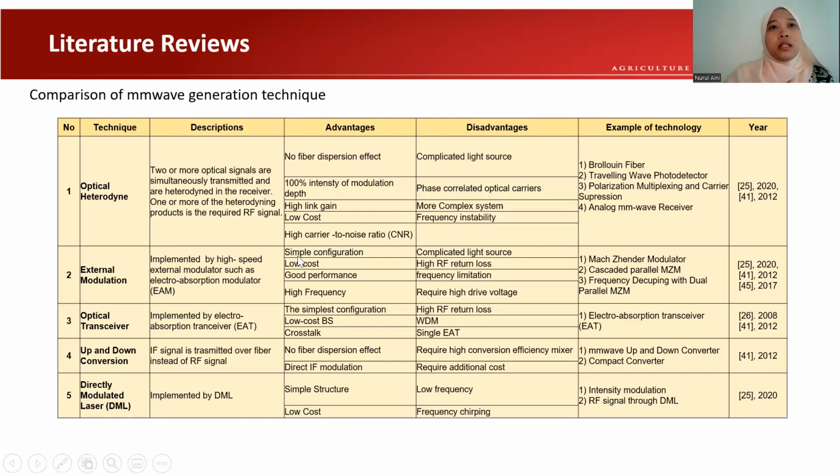So it can be seen for external modulation, the advantages that we have are simple configuration, low cost, good performance, and high frequency. The disadvantages are a complicated light source, high RF return loss, frequency limitation, and sometimes it requires high drive voltage. Examples of the technology are MZM, cascaded parallel MZM, frequency decoupling with dual parallel MZM, and so on.